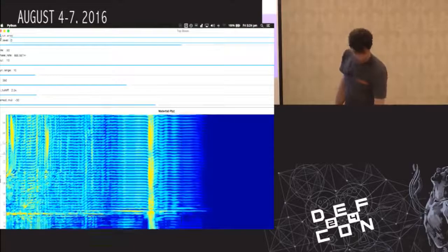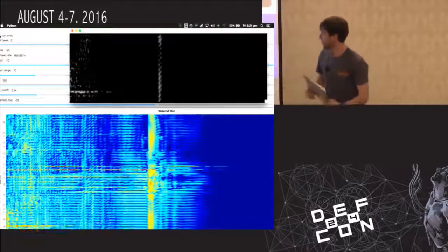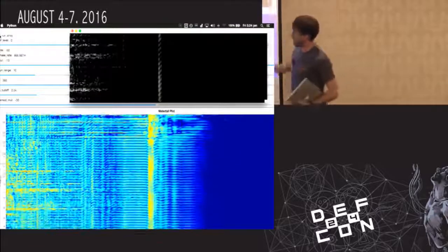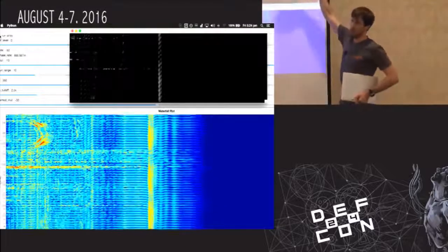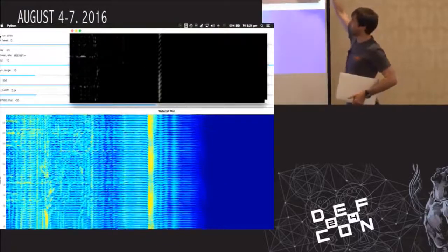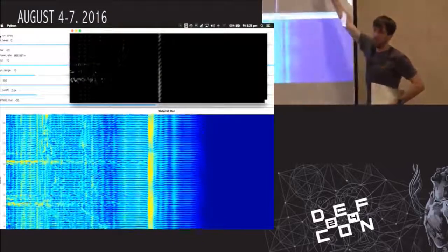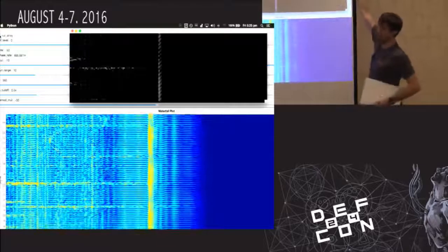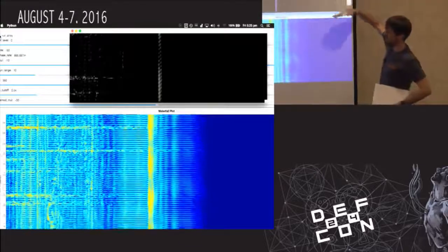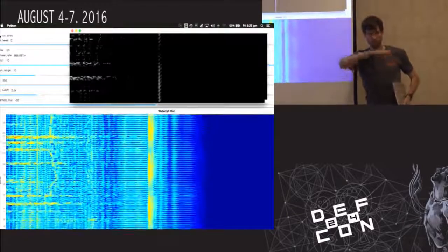So what that's doing is it's processing the FFTs, and then I fix the rate at which it's doing this beamforming, and every time it runs one transform, that builds up one scan line, and then for each of those beamformed angles, it produces each stack scan line. So one of these pictures is supposed to be a full run through the